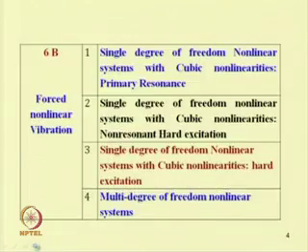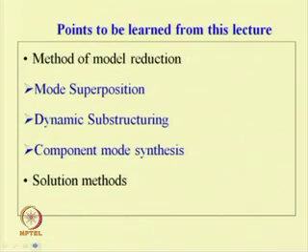So, in today's class we are mainly focusing on the study of multi degree of freedom systems, where we will discuss the method of model reduction. We will discuss the mode superposition method, dynamic substructuring method and component mode synthesis, and the solution we will see by using the harmonic balance method, which we have discussed before.